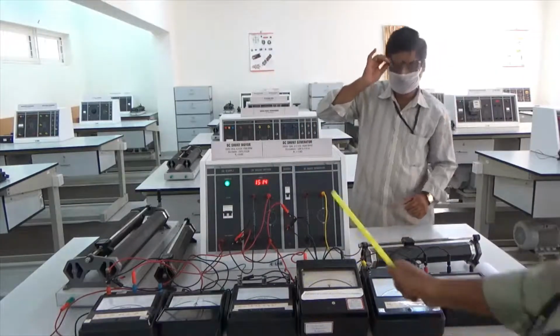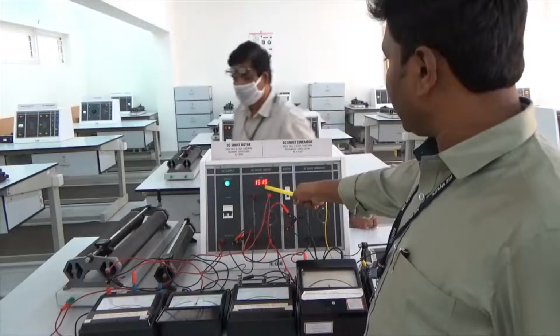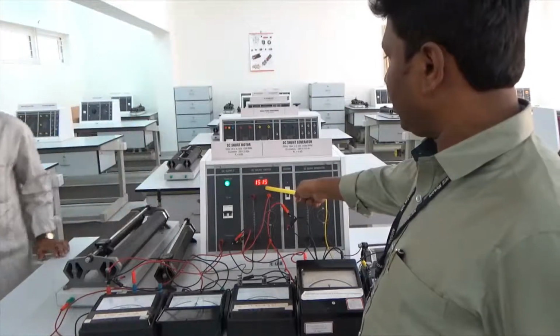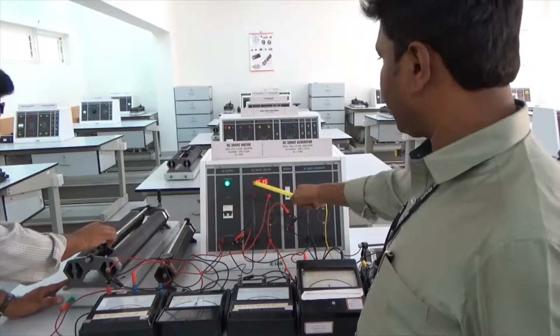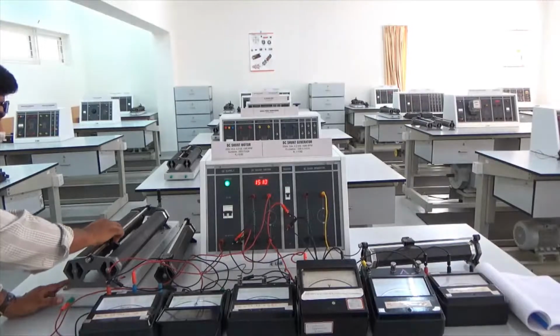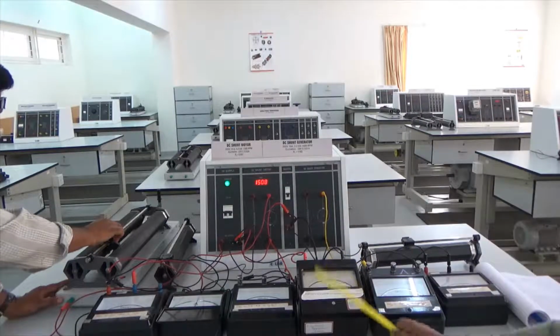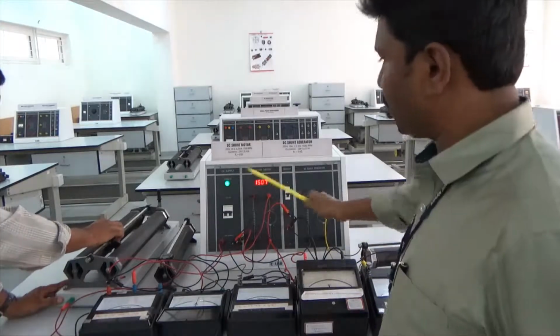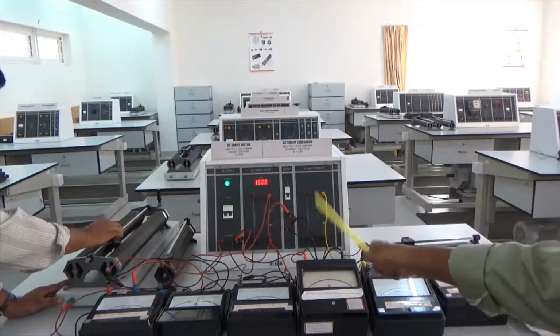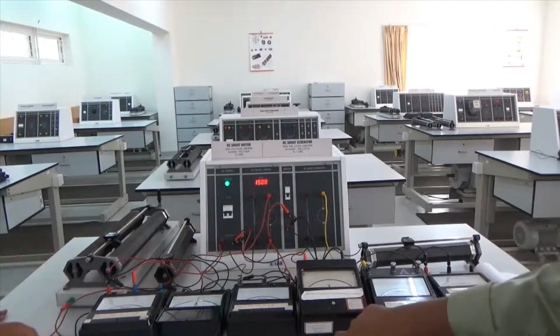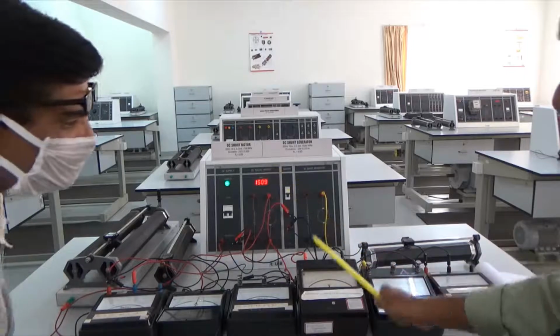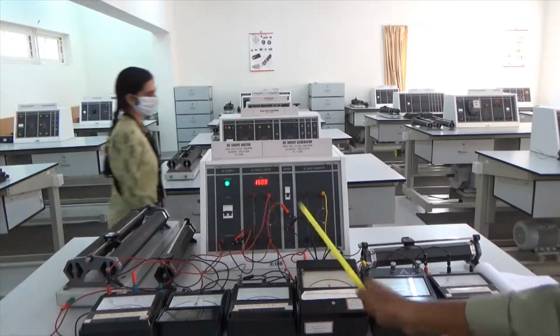Now after switching, there is an increase in the speed here. Okay, you can observe that. You make it the rated speed. Now your generator is in the floating condition after closing the switch. It means it neither takes out current nor injects voltage to this one. So at this condition we will call it a floating condition.